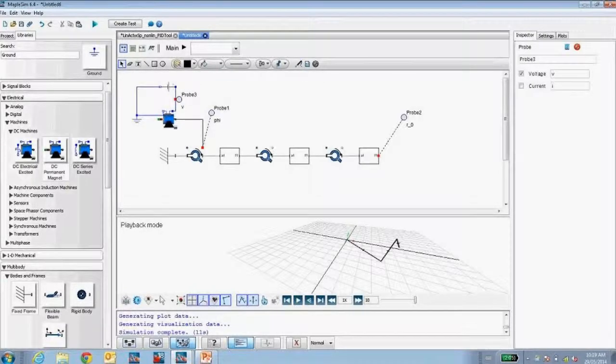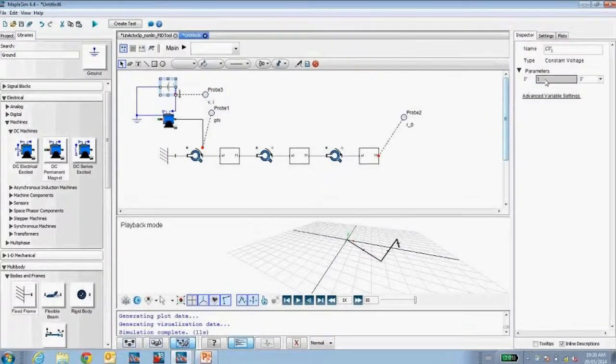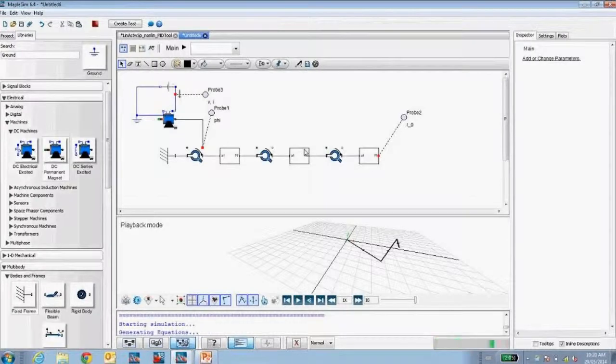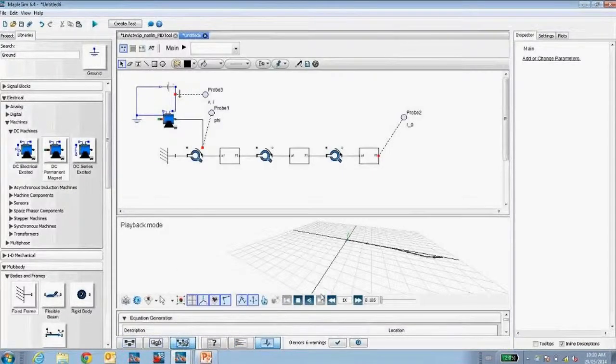By attaching a probe this time in an electrical circuit, you'll see the information that's available to me changes accordingly. So this time I'm able to extract voltage and current through my circuit. And let's run the simulation again. This time the pendulum should be actuated, or should be powered. Okay, we see different results, and let's give a bit more voltage here.